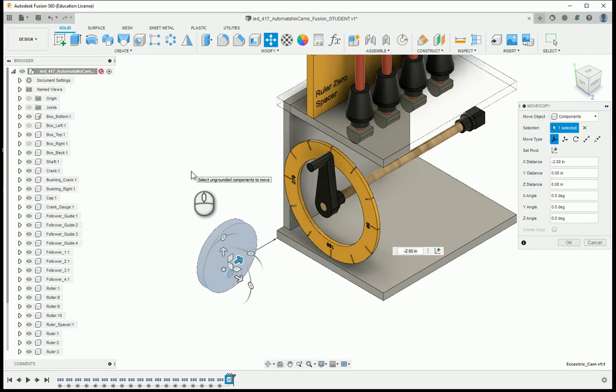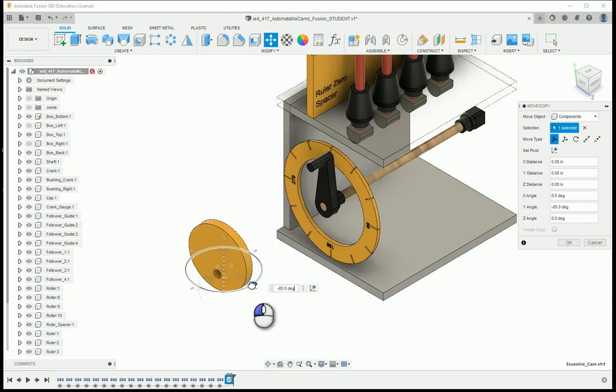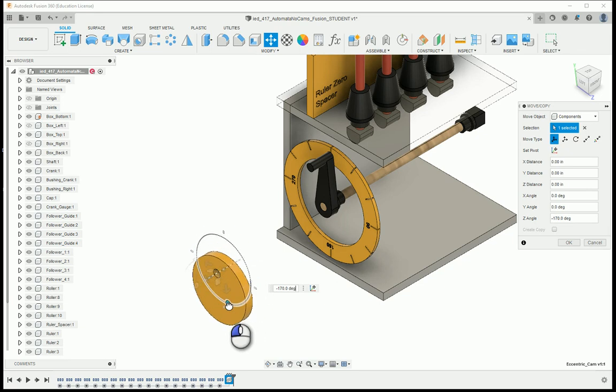With that, I'm going to go through and make sure that each cam is in its lowest position. So I'm going to grab the grips. I want to make sure, one, the cams are facing in the right direction, but also, if I was to install this at 0 degrees, the cam's lowest position that the follower would be at would be rotating this around, so that this would be the lowest position the follower would be in.